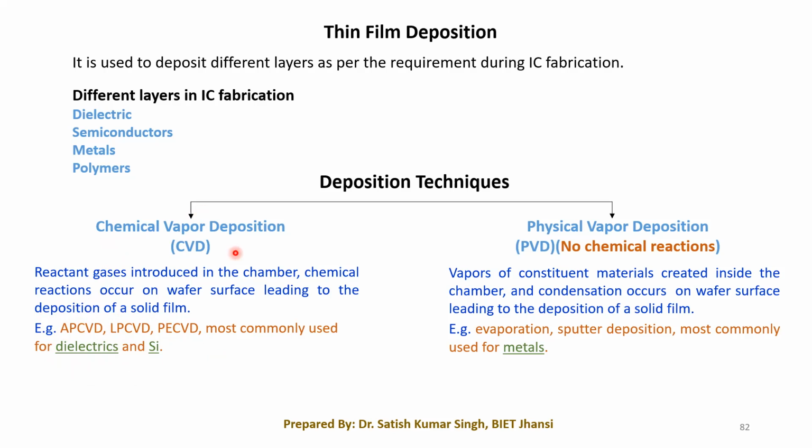the CVD technique. But in the case of metals, if we want to grow metals or any alloys, the same thing cannot be possible by the CVD technique. This CVD technique will not be suitable for metal deposition. So for these purposes, we have to go for the physical vapor deposition processes, in which we have different techniques again, like the evaporation method and sputter deposition. So this will be used for your metal deposition or alloy deposition.